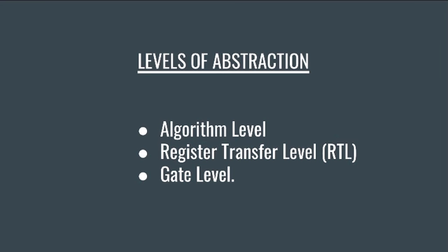Okay, next we have the gate level. This gate level description consists of a network of gates and registers instantiated from a technology library, which contains technology specific delay information for each gate. The characteristics of the system are described by logical links and their timing properties. These signals have discrete logic values like 0, 1, x, z. These gate level primitives can be used to model the design.